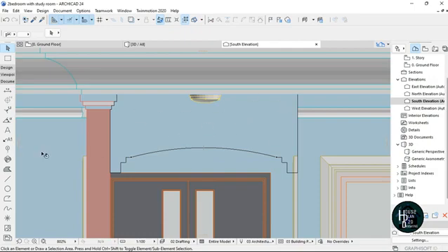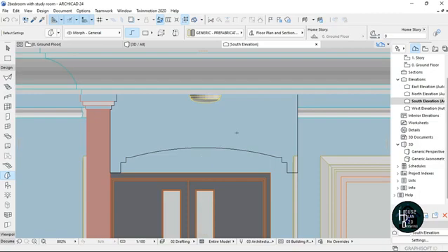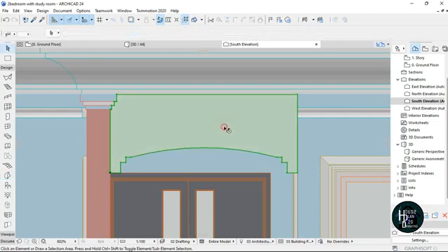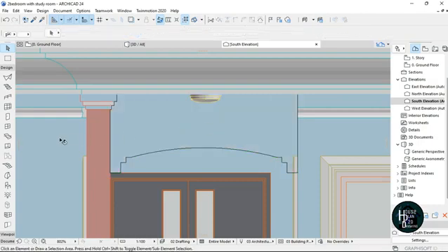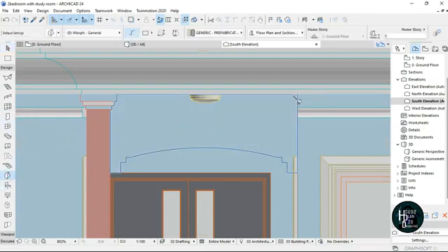So when I'm done like this, I'm going to go to design. I'll click on morph tool, hold down space bar, and click the edge here. When I click it, it's going to turn white. As you can see, it turns white, and that is the morph. But I'm going to delete this because I want to show you guys, just in case you actually hold down space bar and it doesn't give you what you want.